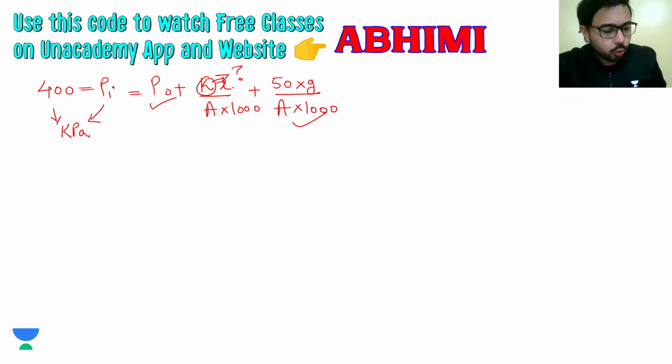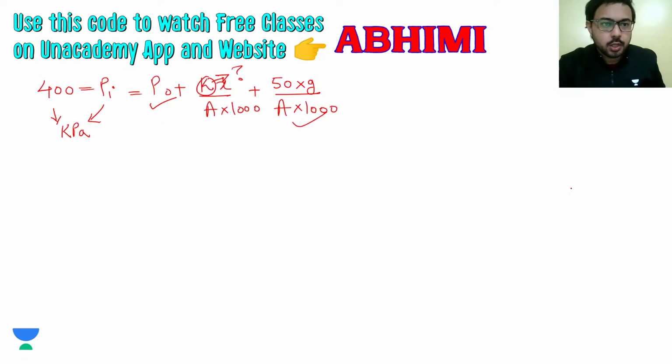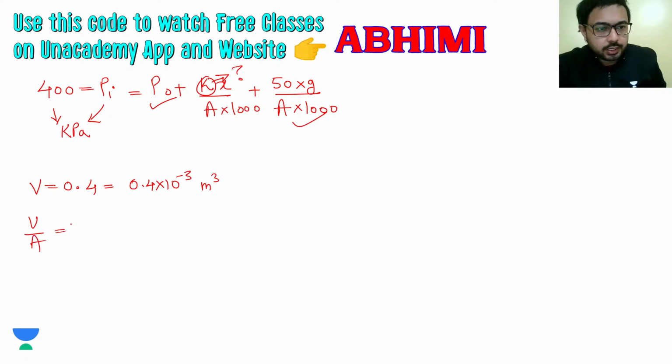But for that we also need to calculate X, that is, what is the height the piston has when the pressure was 400 kilopascal and volume was 0.4 liter. When the volume was 0.4 liter, it means it is 0.4 into 10 to the power minus 3 meter cube. When we divide this volume by area, we can get the value of x.